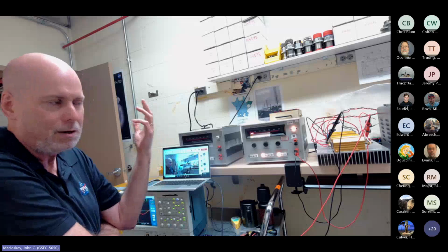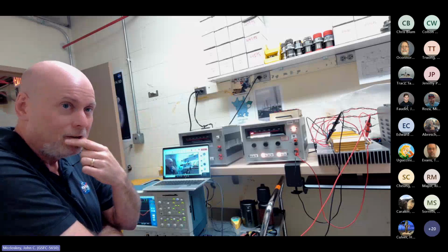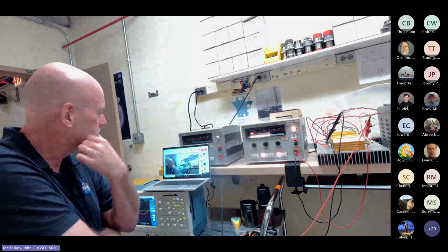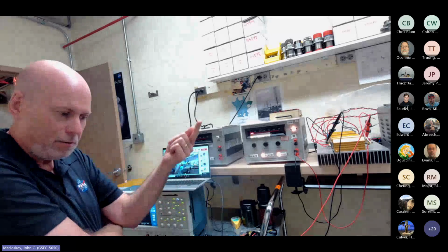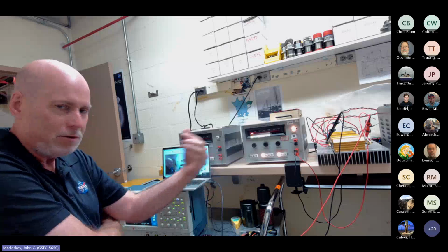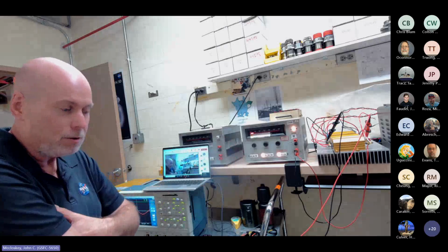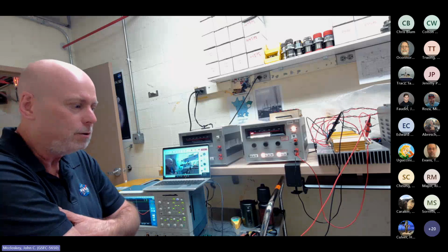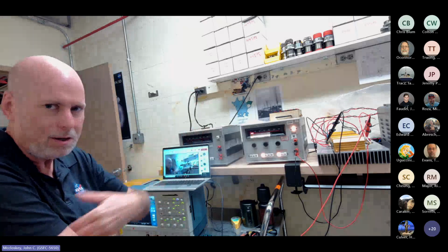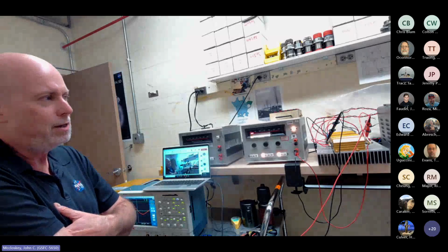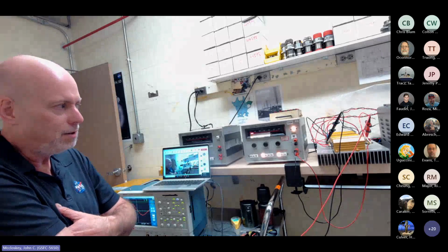Like they're rated, I don't know, 55 volts or something, somewhere right around 56, 58 volts. And then you're going up to 60 volts. That puts some designers into the realm of, well, the parts I was planning to use might not be able to withstand that. I might need to go to another class of parts that can withstand 100 volts or whatever. So that sort of thing can be a significant design driver.